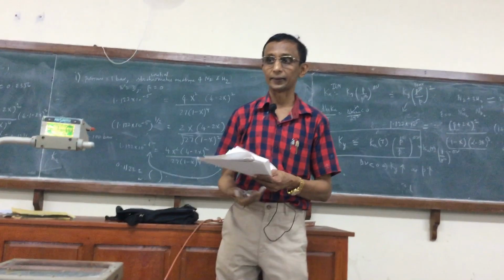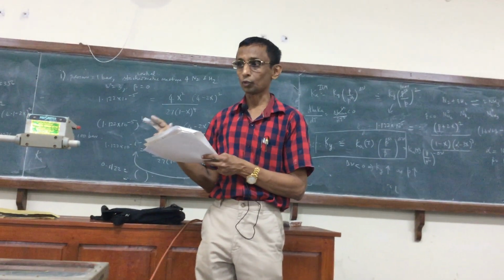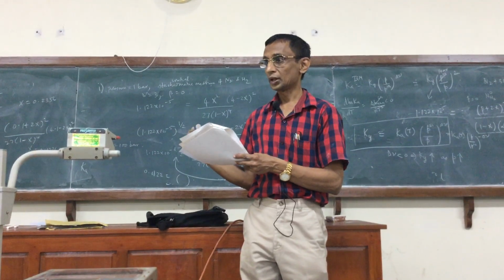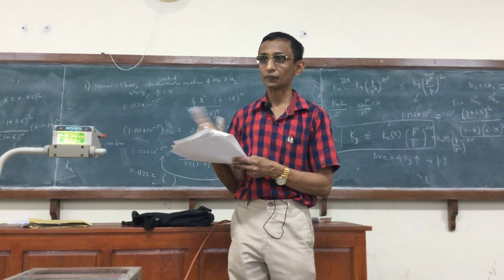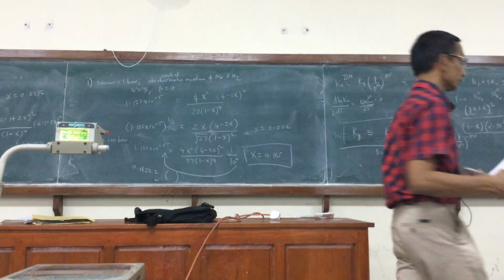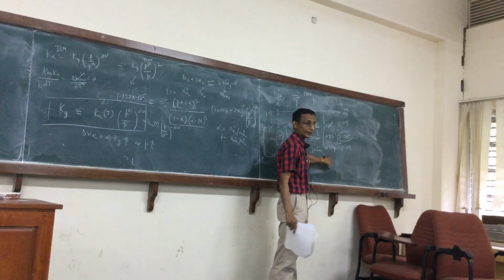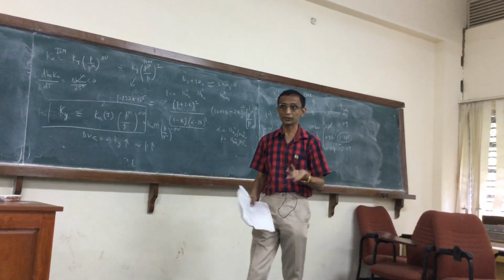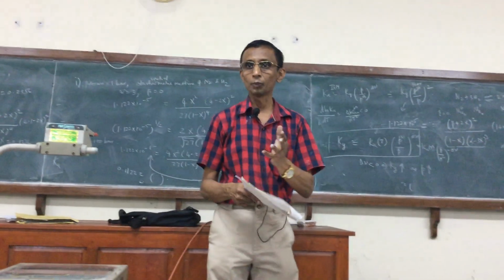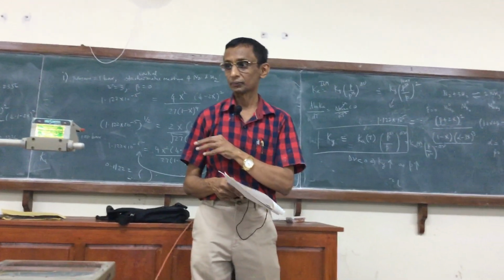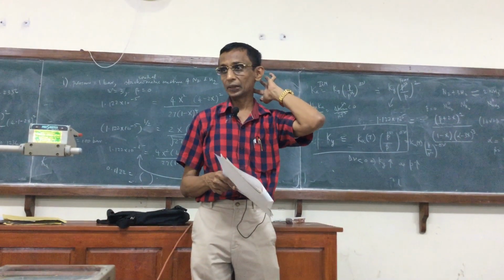That also gets added. We can probably see how much ammonia has been created out of the reaction to truly measure how efficient the reaction is. So when you make these comparisons, you have to keep in mind that here there is initially a certain amount of ammonia, but even though the conversion has decreased, that is simply whatever percent is also added to the final composition. So it's not really a true reflection of how much ammonia has been formed out of the reaction, right? So when you look at absolute values of the mole fraction, you have to keep that in mind.